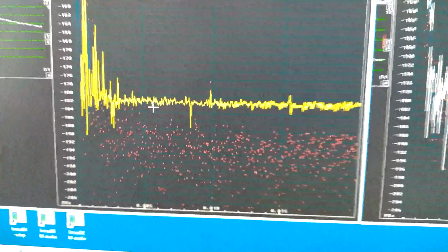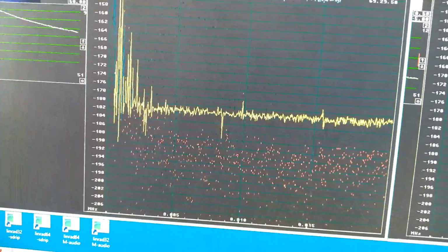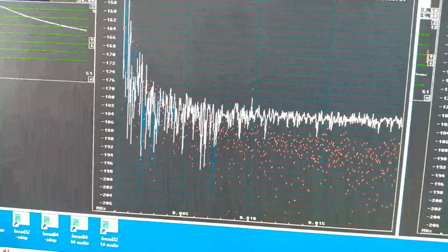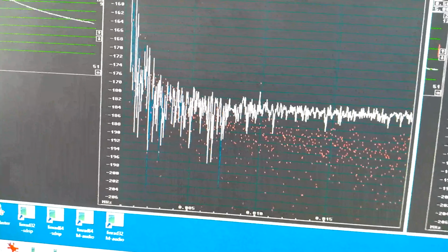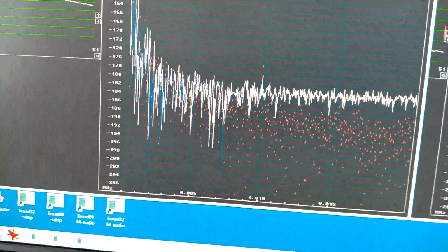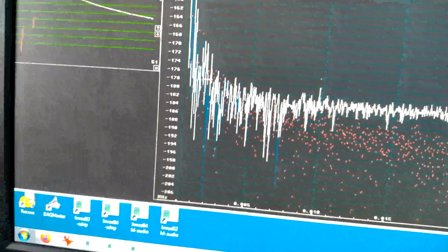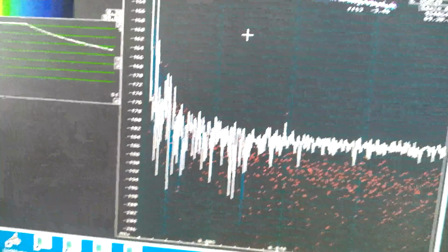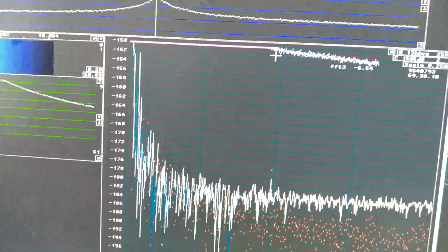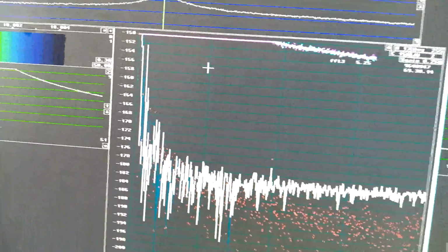I can also have a look at the amplitude noise with the SDR-IP units, and it looks very similar to the phase noise at high offsets, but coming close to the carrier it is more noisy, and that's natural because there is AM noise in the SDR-IPs.